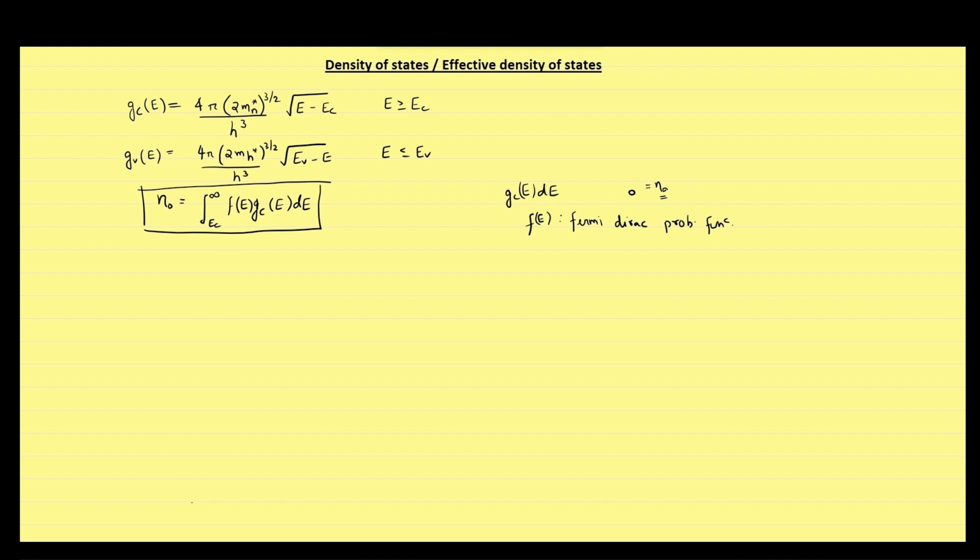You can observe that the number of electrons per unit volume in the integral energy range E is the product of the density of states and the Fermi Dirac probability at the energy level E. Thus, the total electron concentration is the integral over the entire conduction band.